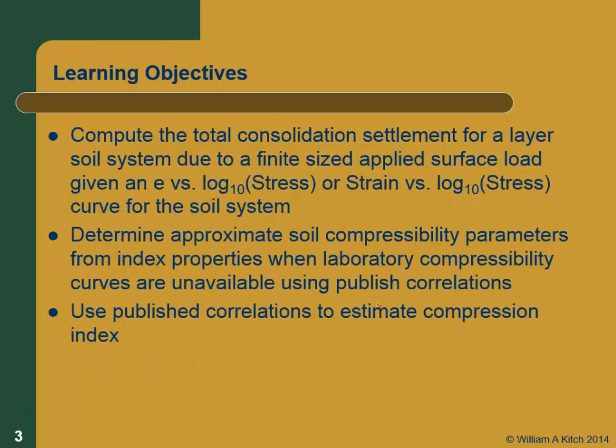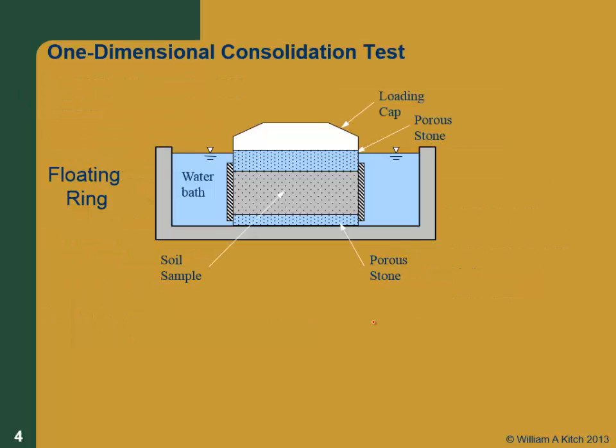And then finally, the thing that you really need to be able to do is to calculate the magnitude of settlement using the e log p method. That's your first task for the project, to actually calculate the settlement that you're going to expect out there. You're free to calculate it either with the e log p method or the modulus-based method, whichever one you think is most appropriate for the data that you have. And we'll talk a little bit about how you can estimate compressibilities even if you don't have data for them.